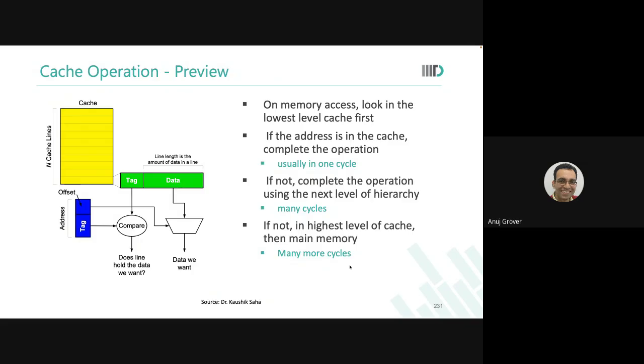So if you have a 32-bit processor, your address bus will be 32 bits long. You have 32 bits of address to identify what you want to bring inside the processor. The processor will give an instruction like load address 1. Address 1 is 32 bits. Now, the memory right next to the processor is L1 cache. That memory is only 1K words big. Just 1K words. If it is 1K words, how many address bits are we talking about? 10. The processor asked for 32 address bits, but you have only a 10-bit address bus available. What will you do?